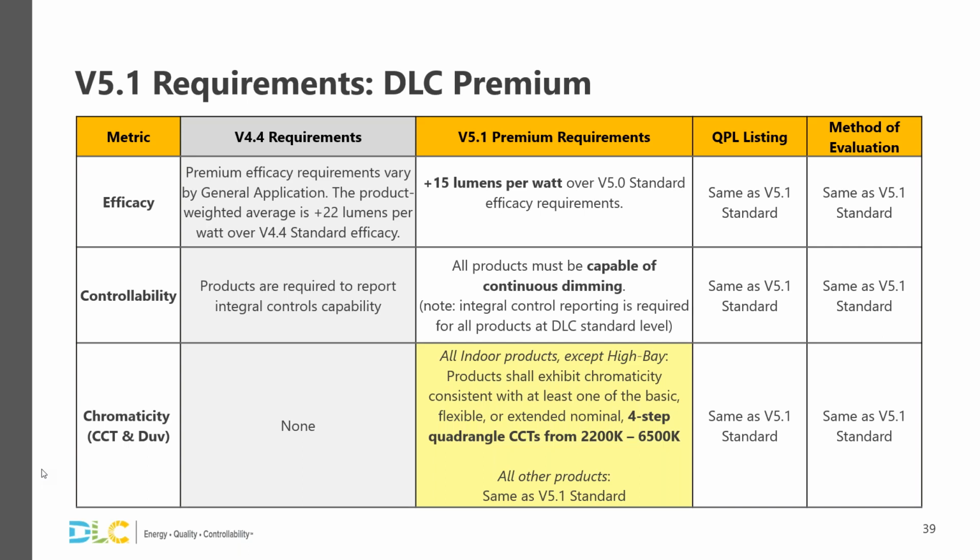We will use the submitted IES files and open them in Photometric Toolbox 32, version 2.7 or later, to see if they comply with our UGR requirements. So there's no requirement for this to be in the test report. We will calculate it independently. Thank you. Great, thanks.